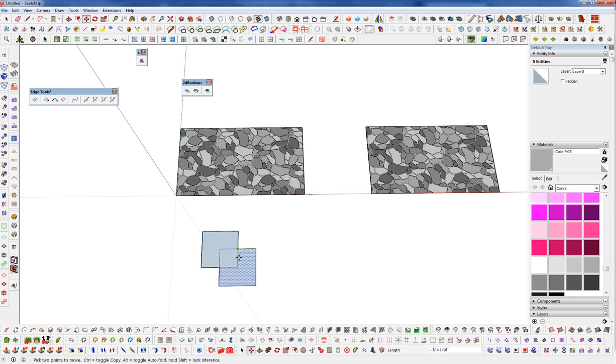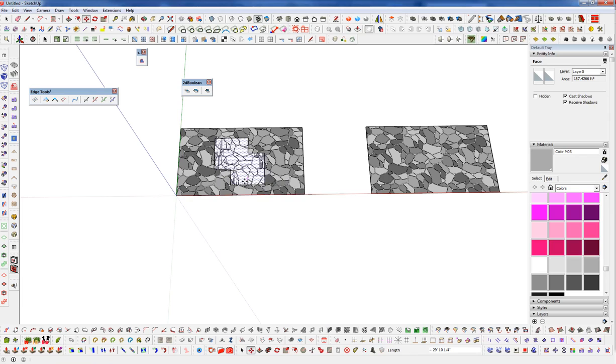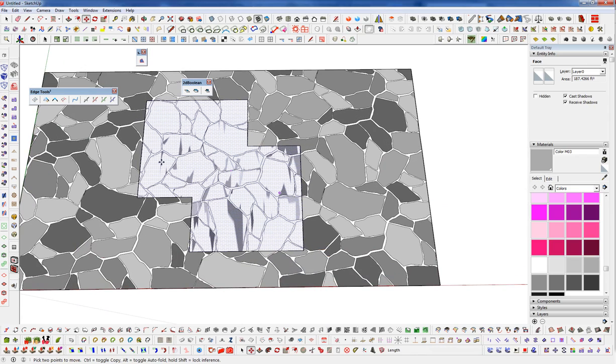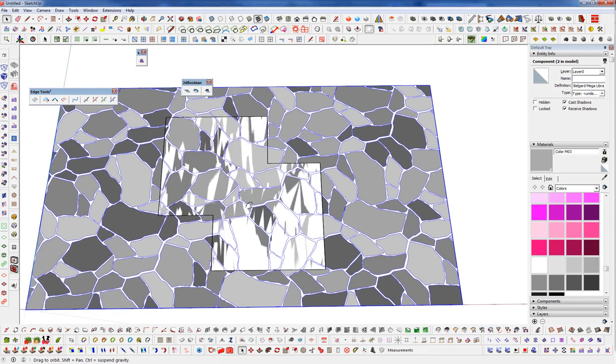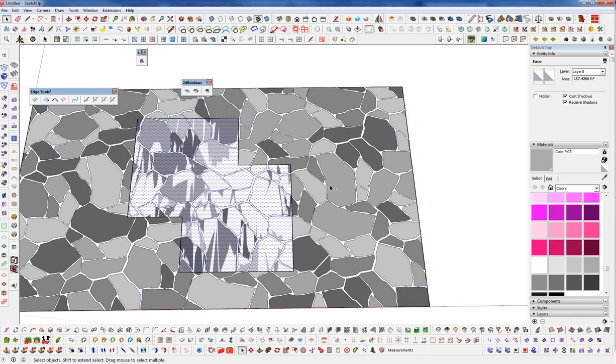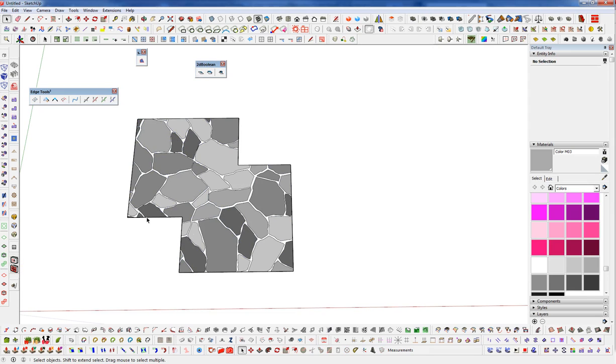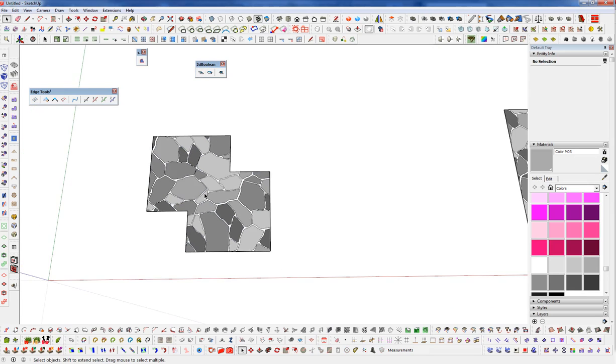Let's do this midpoint to this midpoint, erase the center, reverse those faces. Now if we move this on top here, we want our shape to be not grouped, so ungrouped, something like this, and our hatch here, which we've cleaned up, welded, and textured, to be grouped. So what we'll do is we'll select our face, we'll select our hatch, and with 2D Boolean we can just run the trim option, and that'll trim that down to the shape that we want.